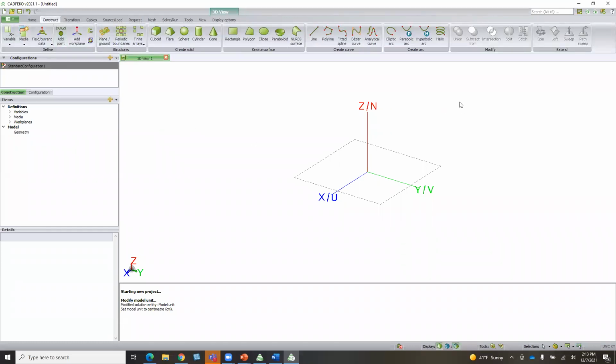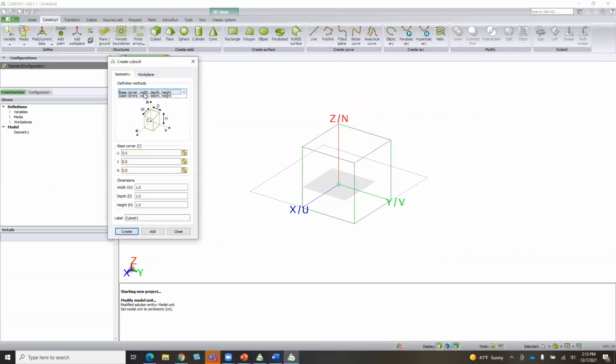All right, so let's create this horn antenna. Those of you who are familiar with horn antennas will know what I'm talking about, but once I get this created, you'll see what it looks like. So I'll go to my solid. I'm going to create a solid rectangular prism on the bottom, and then create the flared antenna portion on the top. So key in my sizes here.